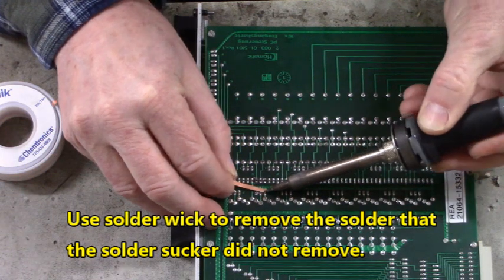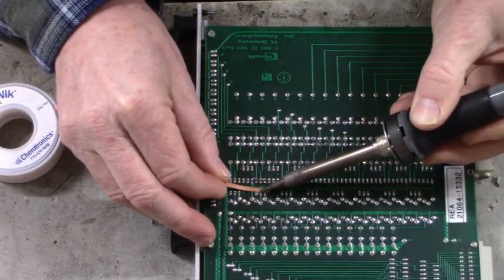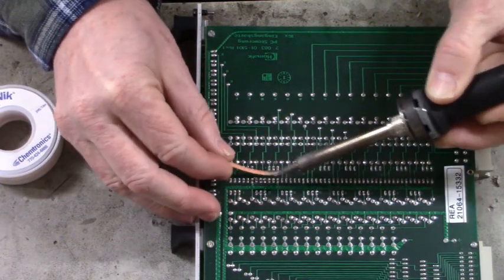The solder sucker never removes all the solder from the vias of the circuit board, so I use solder wick to wick out that solder that the solder sucker never removed.